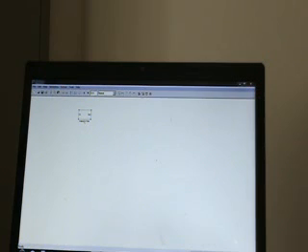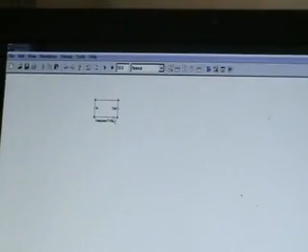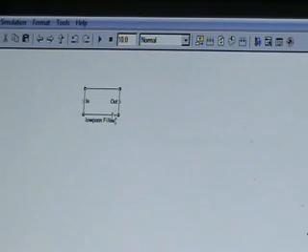Now in MATLAB we click on Simulink. This is the button which is used to open Simulink. Once we open this, here we have a filter. Now we need to give some random values and check whether this filter is meeting the specifications. The cutoff frequency of this filter in the normalized frequency panel is 0.6.